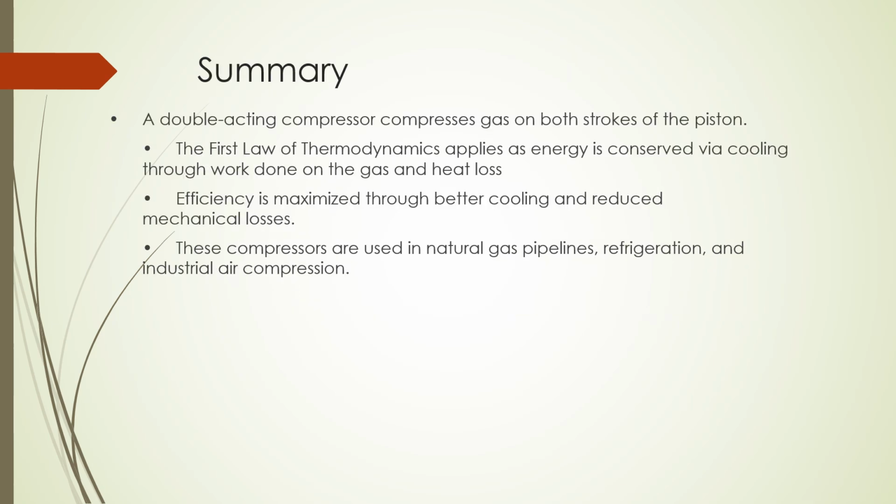A summary of a double acting compressor. A double acting compressor compresses gas on both strokes of the piston. The first law of thermodynamics applies as energy is conserved via work done on the gas and heat loss through cooling. Efficiency is maximized through better cooling and reduced mechanical losses. These compressors are used in natural gas pipelines, refrigeration and industrial air compression.